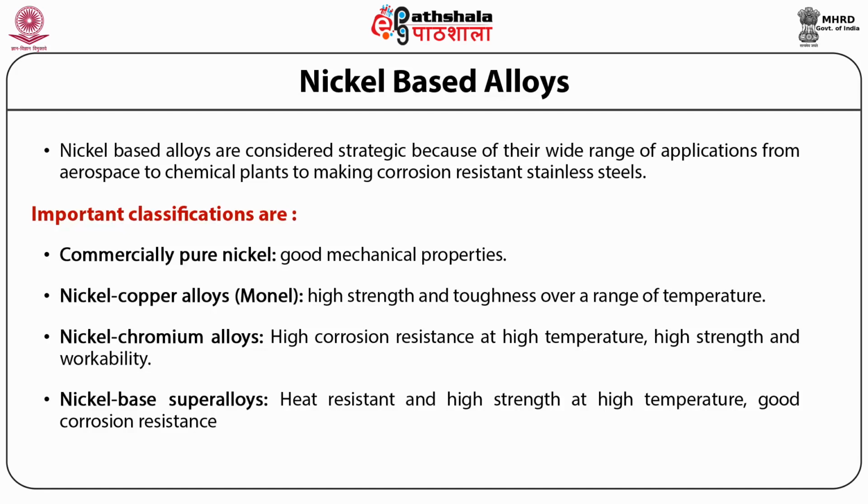Major application fields are aircrafts, space vehicles, rocket engines, industrial gas turbines, high temperature applications, nuclear reactors, submarines, steam power plants, petrochemical equipment, etc. Iron is added to replace some of the nickel as it has lower cost in case of nickel iron superalloys. Therefore, it is used at lower temperatures.